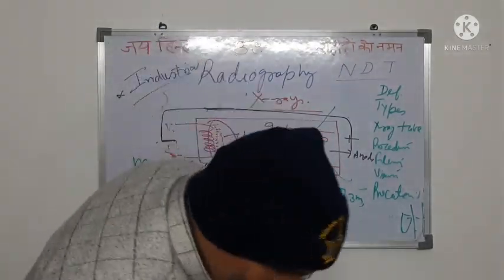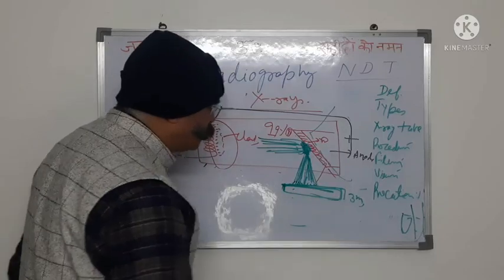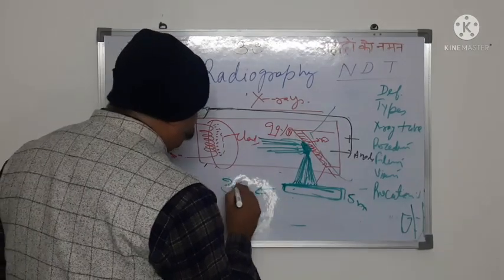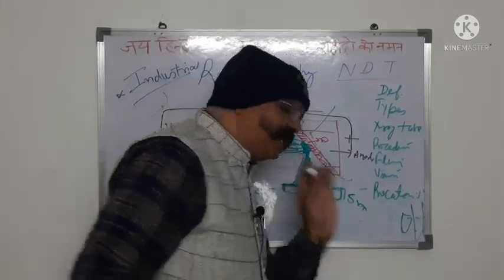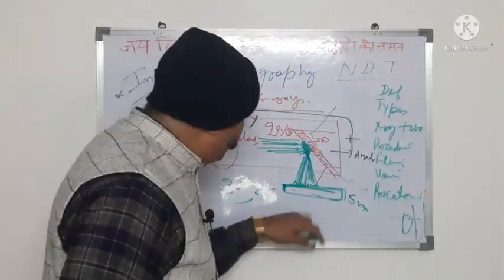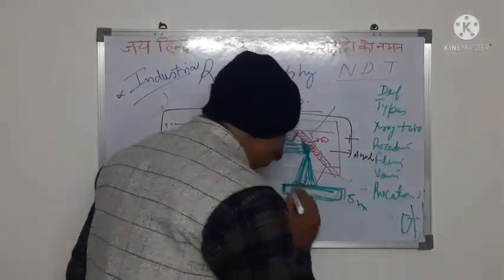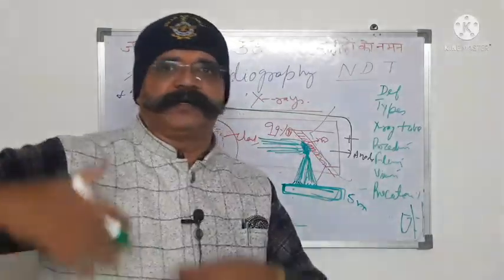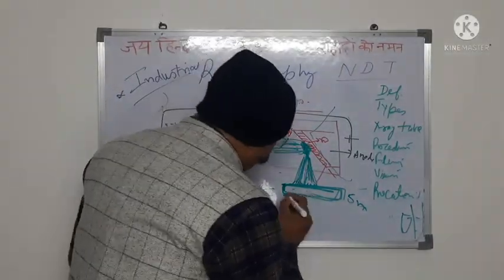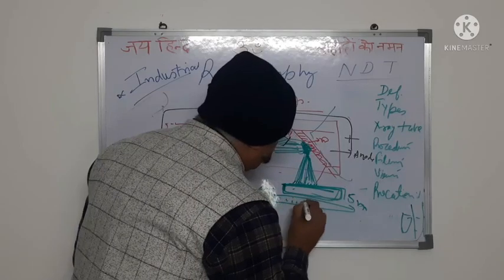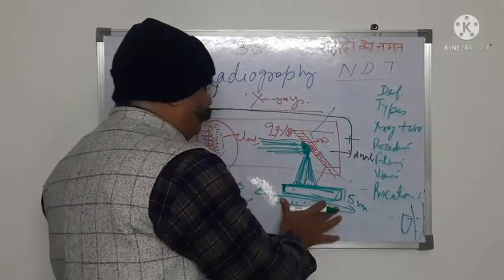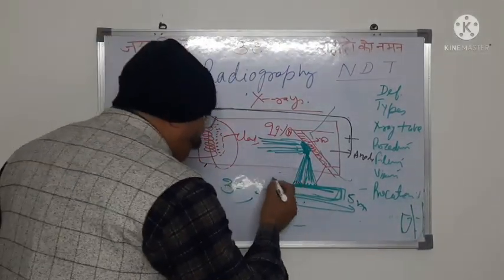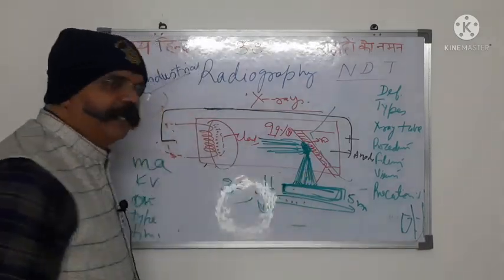Now, contrary to that, you have a 5 mm thickness object and you have allowed it for just 30 seconds. What will happen? These X-rays with this energy may not be able to penetrate completely as its thickness is very high. The material density, strength and some other factors are very high. So they may not bring the proper information in the form of darkening the X-ray film in the same proportion. So the setting of this timing for the complete penetration of the material is very important.